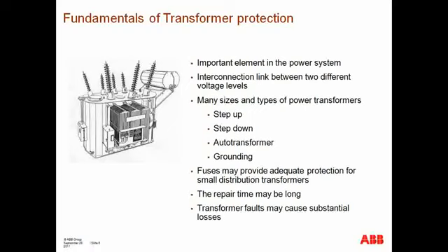Under certain scenarios, a grounding transformer, also commonly known as a zigzag transformer, could be applied to provide a source of zero sequence currents and grounding for a particular network. There are other types of transformers that are utilized. You also have power reactors that are utilized to provide reactive power injection onto the power system. You also have phase angle regulating transformers that aid in controlling power flow between two points within the network, and so on.